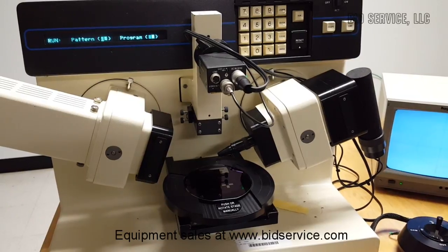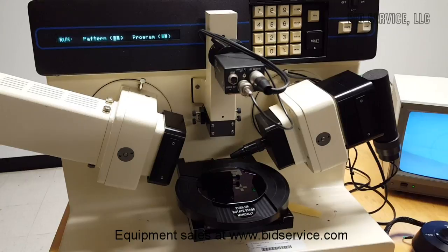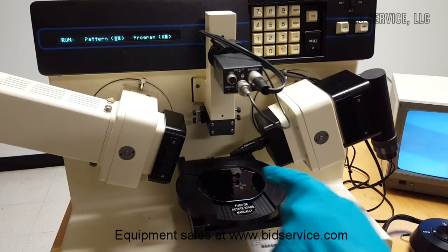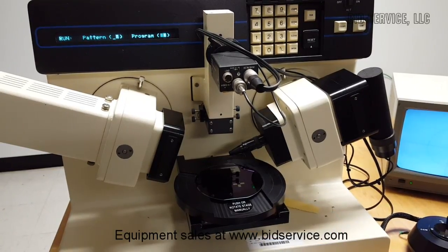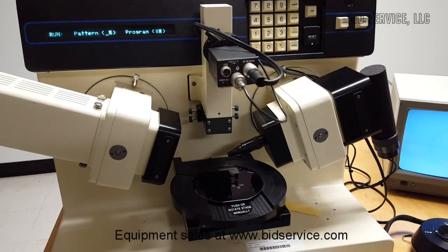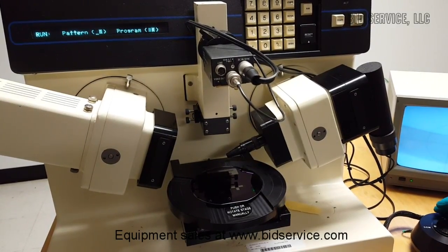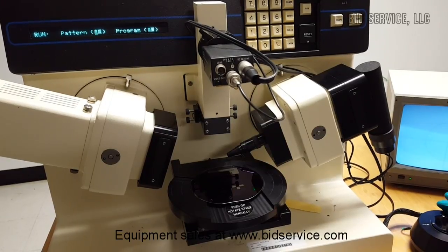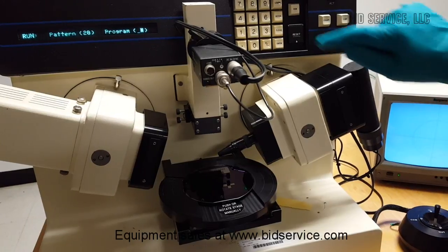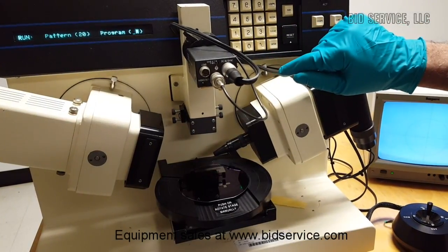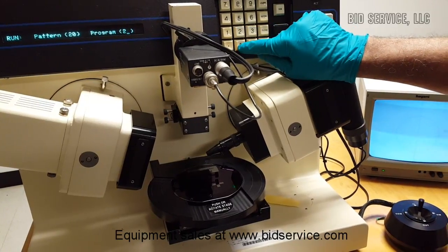In the operation, there are several patterns we can enter. These pattern numbers are like a measurement at the center of the wafer, or 5 measurements at the center of the wafer, or measurements around the wafer, or it is also programmable. The user can move the stage in and out or to the desired location using the joystick and measure. Right now I'm entering 20, which is for a single measurement of the center of the wafer, and I'm going to select program 20,